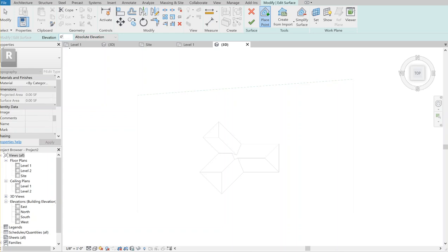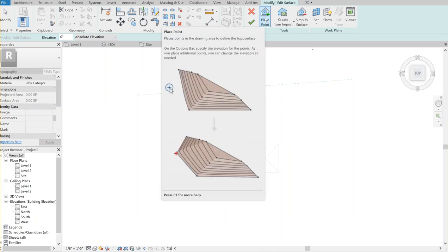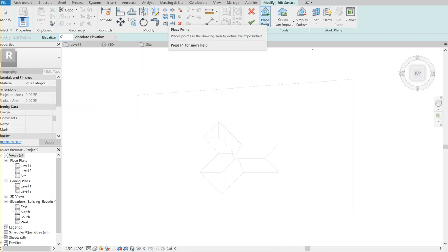So move your cursor over where the elevation says. It's a tiny little screen in the top left corner, right over here. Set it to elevation 0. If there is a relative 0 elevation in your land line, we're going to move our cursor and place a point where it says, on the right check mark over here. So this particular elevation you want to be 0 elevation.